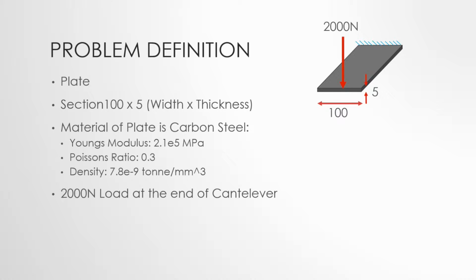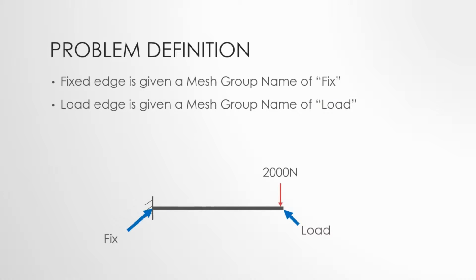The mesh for this FE analysis is in MED format. In this mesh, the fixed edge is given an edge group or a mesh group of fix, and the edge on which load is applied has been given a mesh group of load.